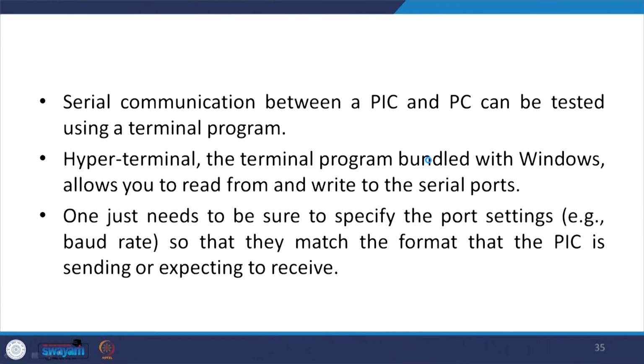Serial communication between PIC and PC can be tested using a terminal program. HyperTerminal, the terminal program bundled with Windows, allows you to read from and write to the serial ports. One just needs to be sure to specify the port settings, such as the baud rate, so that they match the format that the PIC is sending or expecting to receive.